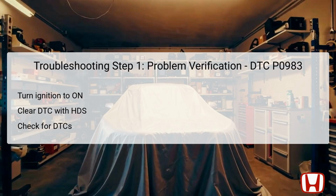The first step in troubleshooting DTC P0983 involves verifying the problem. Start by turning the ignition switch to the on position without starting the engine. This activates the vehicle's electronic systems. Next, utilize the Honda Diagnostic System, HDS, to clear any existing DTCs. This step resets the diagnostic system and allows you to capture current data accurately.